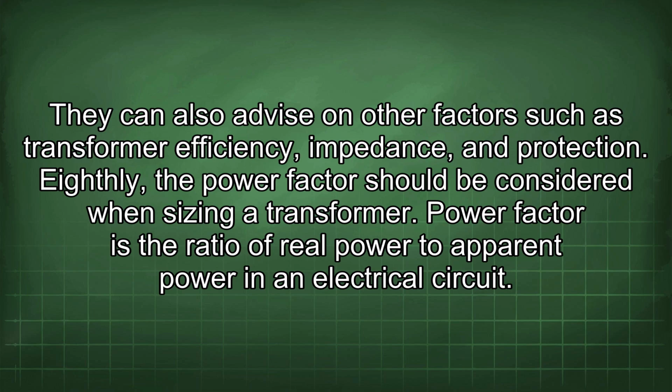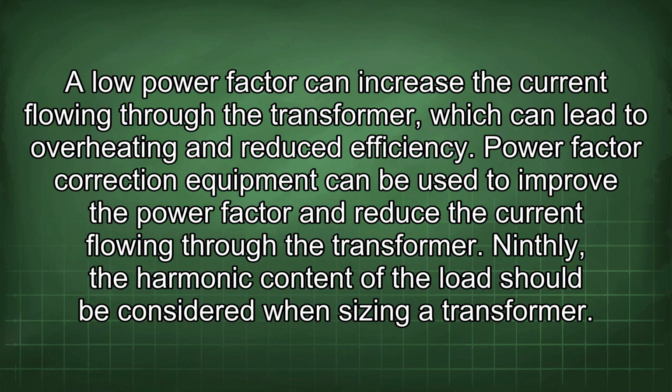Eighthly, the power factor should be considered when sizing a transformer. Power factor is the ratio of real power to apparent power in an electrical circuit. A low power factor can increase the current flowing through the transformer, which can lead to overheating and reduced efficiency. Power factor correction equipment can be used to improve the power factor and reduce the current flowing through the transformer.